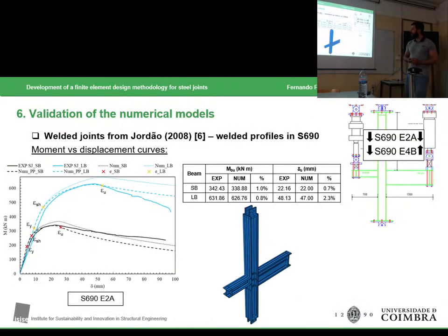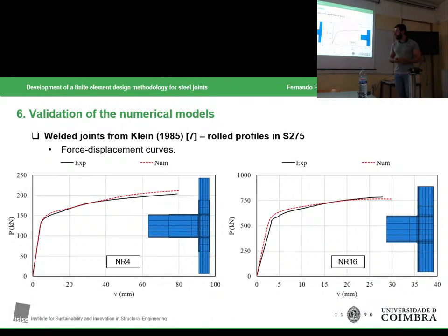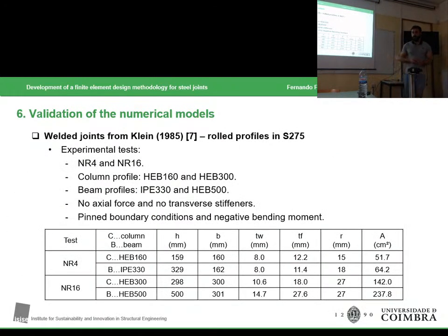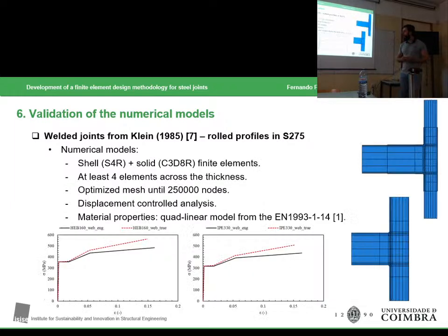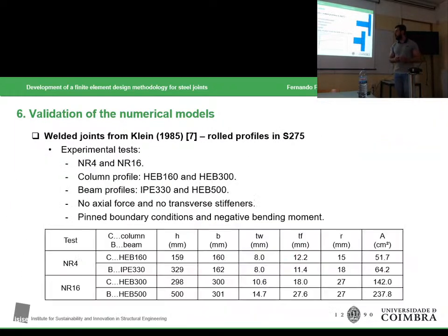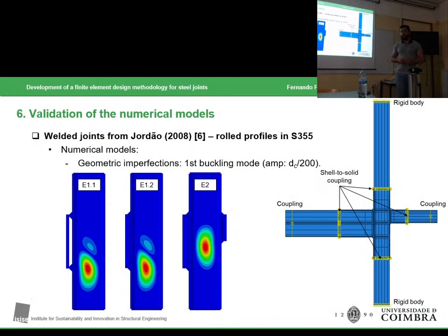So from Sandra Jordão, there is a mention that she measured the final deformation of the joints and tried to input in her models a similar shape to obtain that, but it wasn't measured before the test, it was after. Your model in the first buckling modes gave good results, and you don't know what they did, so maybe. These are the buckling modes. We follow the guidelines for this case.